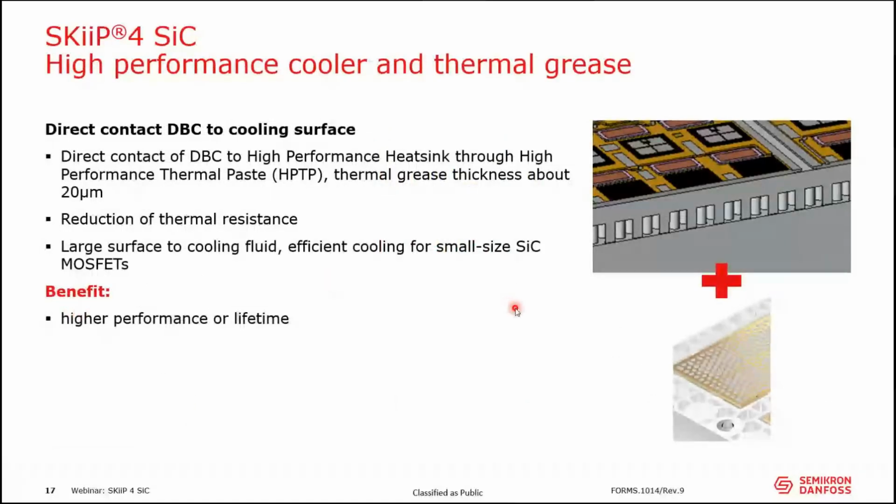Now we are coming to our high-performance heatsink. In the areas where we have the chips, we have pin fins. The structure of the pin fins is optimized to get the best possible thermal performance, because the silicon carbide chips are quite small and the concentration of heat is quite high. So it's very important to have appropriate cooling to get much more power out of the module.